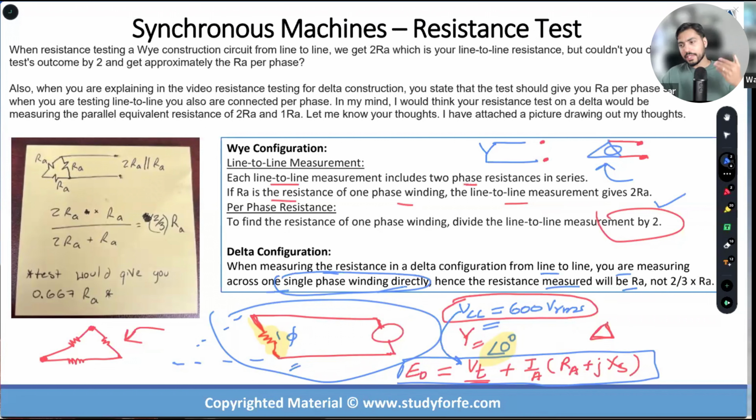So over here, if you take a step back and look at the question that you asked, and the knowledge pieces that we had to deploy in order to effectively answer this question, there are plenty. Delta Y configuration, differences between them, phasor diagram, your three-phase square root 3, 30 degrees, reference voltages. Understanding the equivalent circuit of the synchronous machine as to why this equation is the way it is. Because if this was switched to a motor, there are going to be changes in this equation, and that will have implications. Okay.